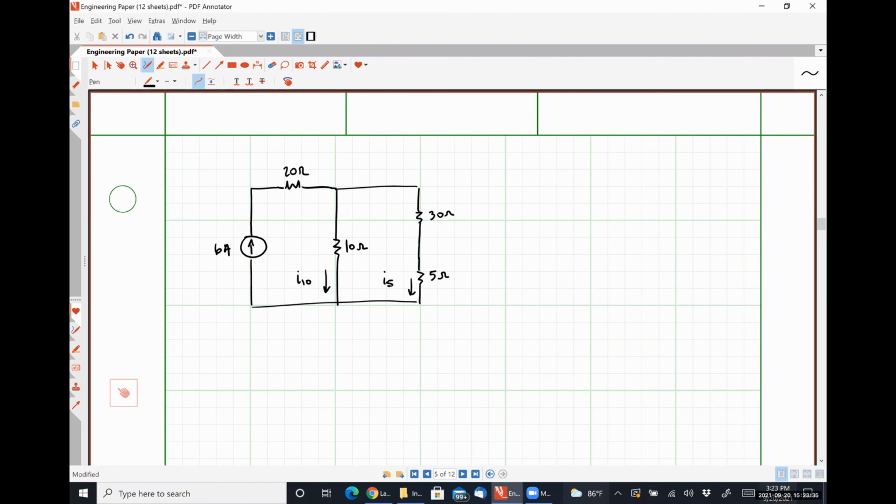All right. So this guy is appreciably different from our last example in 2 ways. One of our parallel branches here has been split up into 2 resistors in series. I feel like you guys can catch on pretty quickly as to what we're supposed to do there. But what about that 20 ohm resistor to the top? How does that mess things up, if at all?